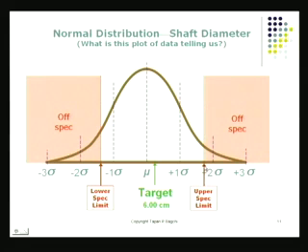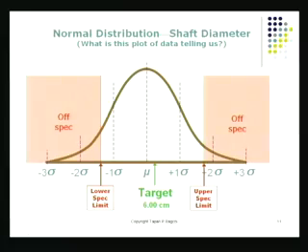Now, there is a limit here which is called the upper spec limit for the parts. And this is the upper spec limit, which says that if I produce parts which have dimensions beyond this upper spec limit, those parts are going to be useless for application. So, in fact, if I was producing these caps, and these caps were produced with too wide holes, again those would be useless to be used in the assembly of pens. In fact, it might turn out that those caps would end up in the off-spec area, either to the left, which is like the caps are too tight, or they might be too loose, which is to this side. Both of these are harmful.